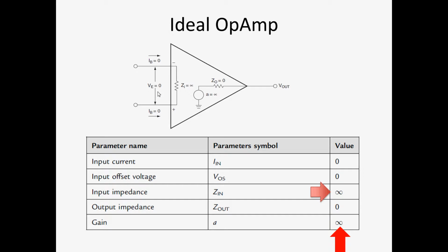In the case of the human body, you want to measure the voltage out of the brain, the EEG. You put a bunch of amplifiers in parallel with the electrodes, or where the EEG needs to be recorded. And you wish that the input impedance of this amplifier is as high as possible, ideally infinite.